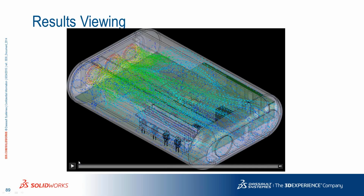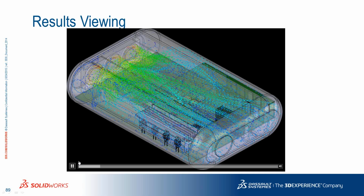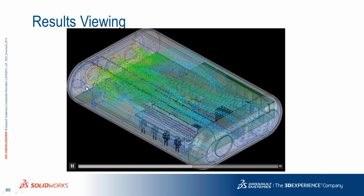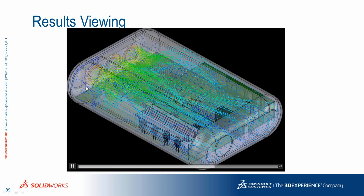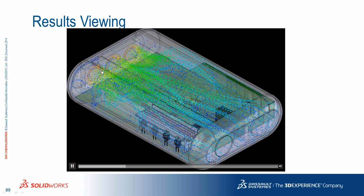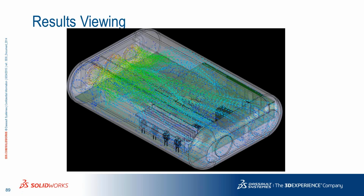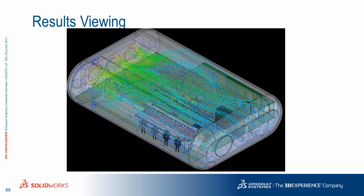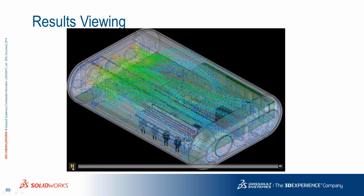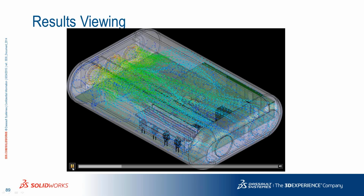One of the nice things about flow simulation is what we call flow trajectories. And this is showing us, and hopefully it's not too choppy over the internet connection, how the air is coming inside, being sucked in through these fans on the left end, and how that air is moving inside of this enclosure. It circulates inside, and then it finally exits out of these 3 ports on the right side of the packaging. So it's a great way to understand, optimize, or look at airflow patterns.